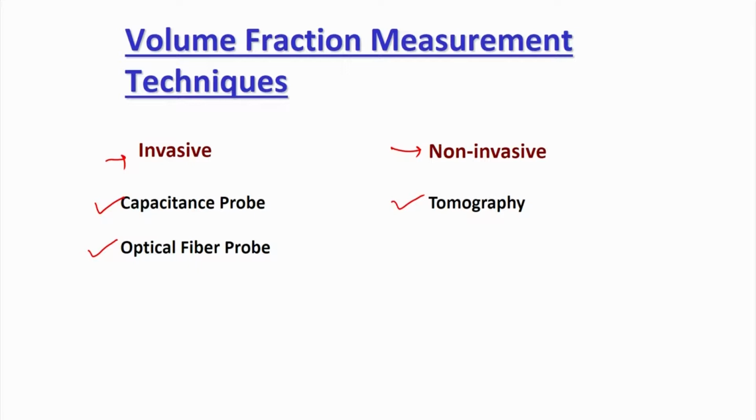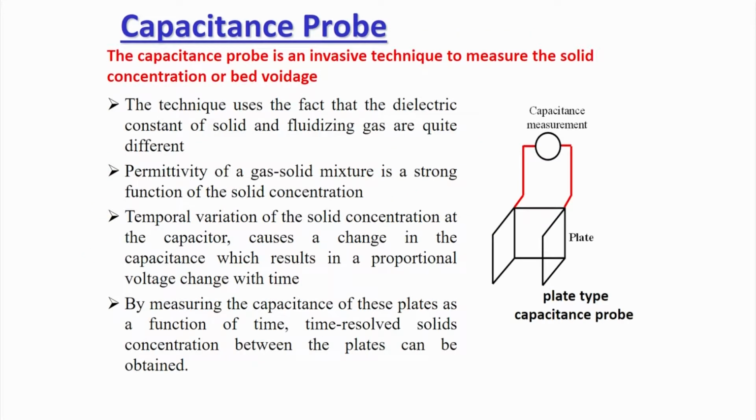These techniques are still popularly used to measure the volume fraction because they are very cost effective. We will see how you can improve the technique and what the basic working principle of each is. So, let us begin with the capacitance probe. As I said, it is an invasive technique to measure the solid concentration or bed voidage. Suppose you have a gas solid fluidized bed and want to find the solid concentration, solid fraction or bed voidage; this technique is widely used.